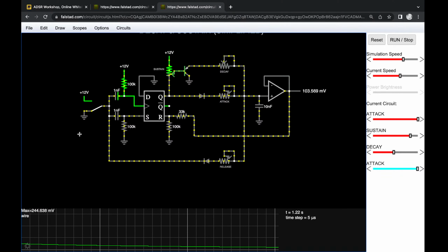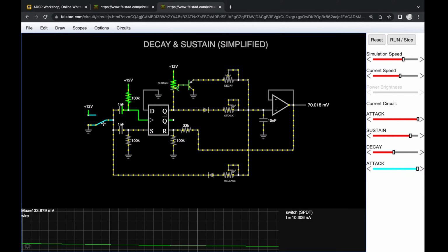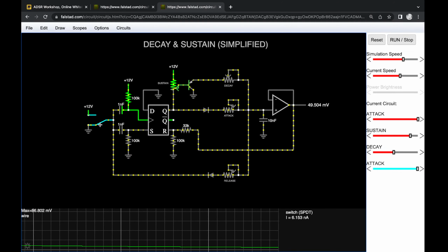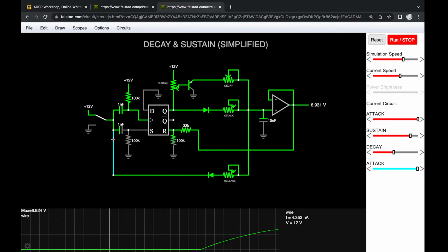The way this works is, if this key is pressed, then the voltage here is going to be high, 12 volts in our case. And that means that this diode is pressed shut, right? Because the voltage here is the highest voltage that we have in our system, 12 volts. And that means that nothing will flow out of here simply because we've closed it, right?